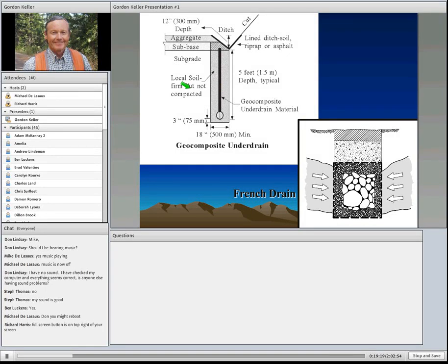The other traditional type of underdrain that's been used for probably decades or centuries is a French drain. That's this little thing we have over here. The difference with a French drain is it's just rock. It doesn't have this perforated pipe here. And so the good news is it's less expensive, but the bad news is they're difficult to construct and really have something that works, because you've got to have like a graded filter here. They traditionally weren't made with a geotextile, and so you just had to go from soil to fine gravel or sand to coarse rock in the middle. So you don't have as much permeability or capacity, and they plug more easily if you don't use a geotextile. So today, pretty much folks come back and use either geocomposite drains or the underdrain that I showed in the first place there.